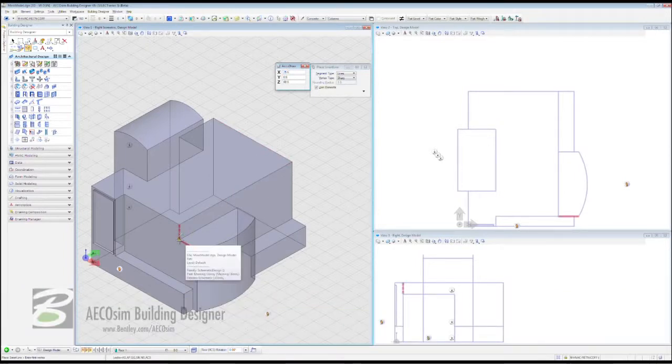And we need to come down to this return just here. Click once, hit the F key to rotate your AccuDraw compass, come all the way down to the intersection here and click, AccuDraw and AccuSnap helping us out to do that so efficiently and coming out into the model. Once you've done that, you head north and you can see AccuDraw, AccuSnap is helping us out wherever we go, throwing out construction lines for us. We need to click there once and there to join this whole thing up, and you see you have this rectangle.